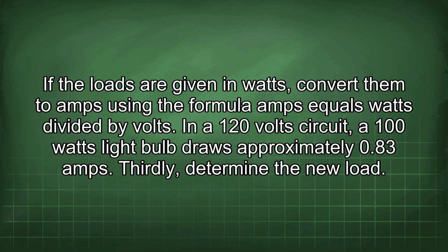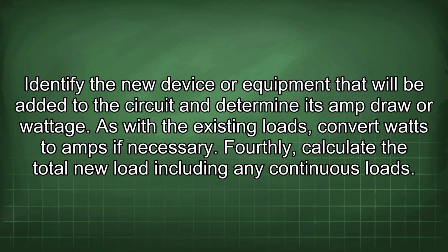Thirdly, determine the new load. Identify the new device or equipment that will be added to the circuit and determine its amp draw or wattage. As with the existing loads, convert watts to amps if necessary.